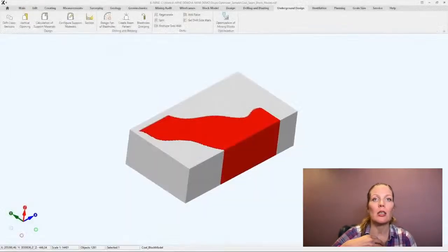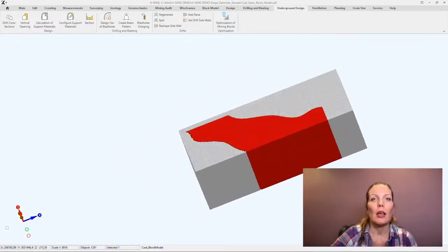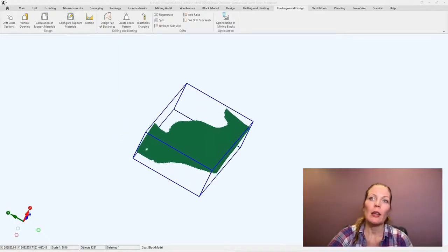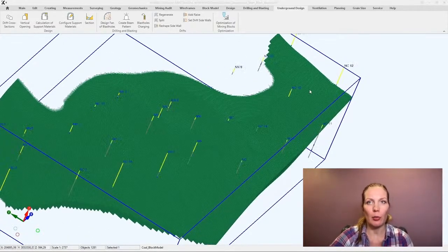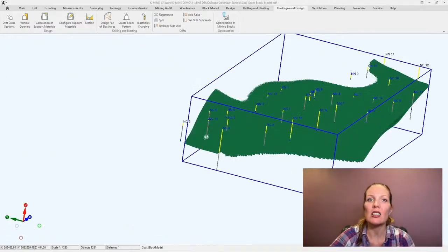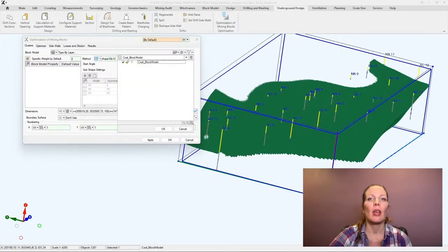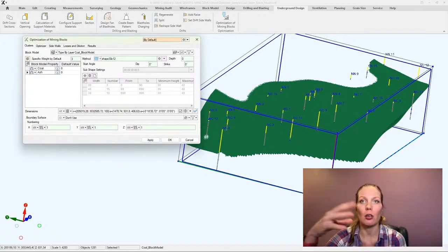The output is a set of stopes already shaped for immediate use in design. Another key feature is the ability to restrict the optimization domain. Not every geometrical stope is practical at a given stage of development. Some areas may be inaccessible from current levels, located within the influence zone of active stopes, or positioned under protective pillars. In K-Mine, the engineer defines the working volume, the portion of the model where extraction is currently allowed.